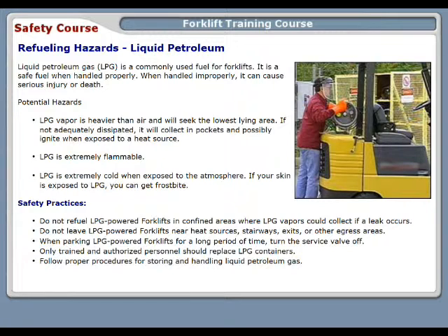LP gas is extremely flammable. Also, LP gas is extremely cold when exposed to the atmosphere. If your skin is exposed to LP gas, you can get frostbite. Safety practices include: do not refuel LP gas-powered forklifts in confined areas where the gas vapors could collect if a leak occurred. Don't leave LP gas-powered forklifts near heat sources, stairways, exits, or other egress areas. When parking your LP gas-powered forklift for a long period of time, turn the service valve off. Only trained and authorized personnel should replace the LP gas containers. Follow proper procedures for storing and handling liquid petroleum gas.